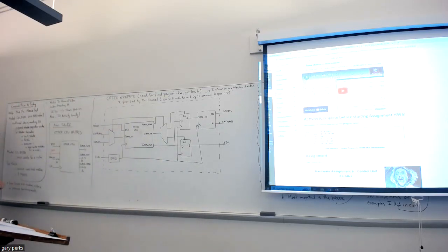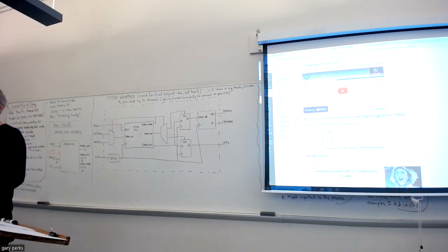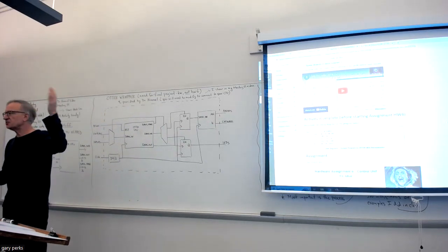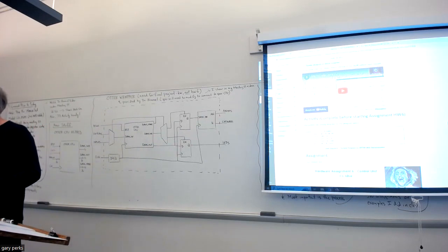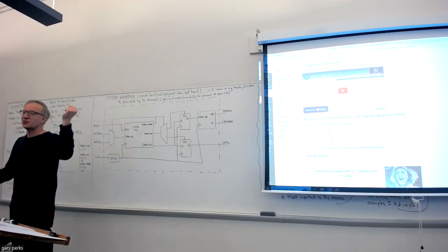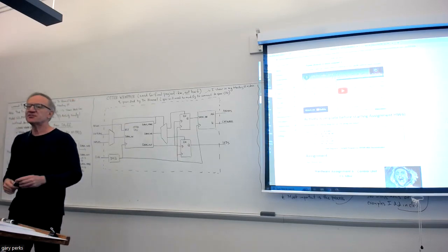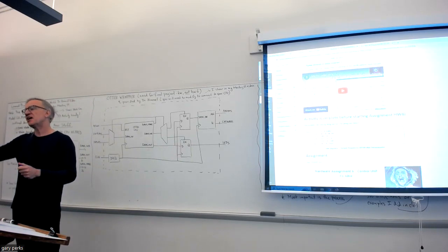So for hardware 6, you have to model the FSM and the control unit decoder. Also, this is when you connect all your lower level modules together. Once you have those control units done, you have all the pieces to the Otter. We've been doing basically one piece per week, and now you have to come up with a top module that connects them all together. You've done that plenty of times. You did it for the program counter, one of the first assignments we did here, and you did structural models in CP133. So you should be very familiar with the code needed to connect up those lower level modules.